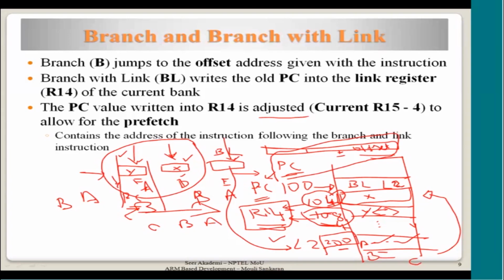So please remember, when you are flushing the pipeline, don't think that A can jump here and start executing, skipping these 2 stages. It is not possible. Until the fetching happens and the decoding happens, an instruction cannot come into the execute stage to get executed. So there is no shortcut. It has to go through the different stages. So effectively 2 cycles, the 2 instructions which were there will get emptied and then the control flows here.